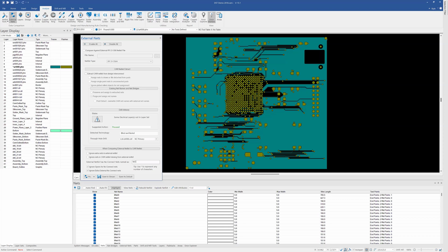Well, the problem was that worked, and the other one, which is pretty common, both of those work fine. But what we started seeing was one CAD system out there doing this: unused 1, unused 2, unused 3, essentially giving them a net name. So now you've confused the software because it's thinking, well, are these supposed to be connected?